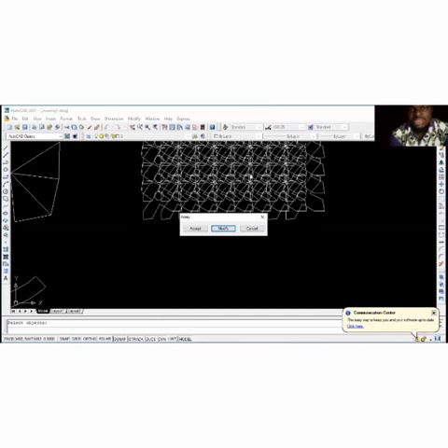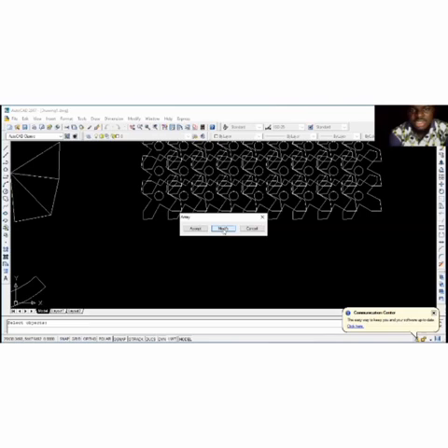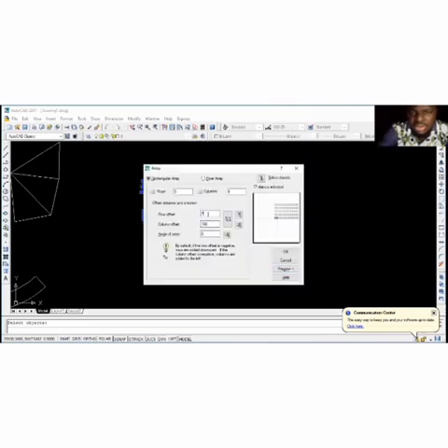Now you can see it's not well arrayed, so let's modify it. So we can modify it by trying to change the row offset. Let's change the row offset to 700 in this place, and then 700 here as well. After which you can preview it. Okay, let's still modify it. Let's change the row offset to 900, and then this 900. Let's preview.